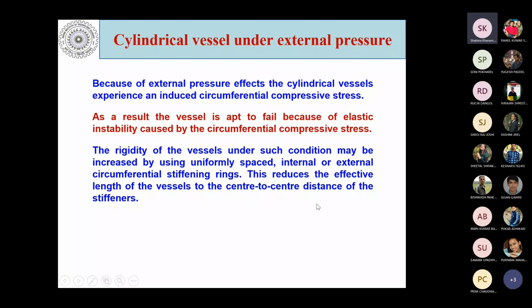Rigidity of the vessel under such conditions may be increased by using uniformly spaced internal or external circumferential stiffening rings. We usually place stiffening rings on either the internal periphery or the external periphery, after regular intervals.